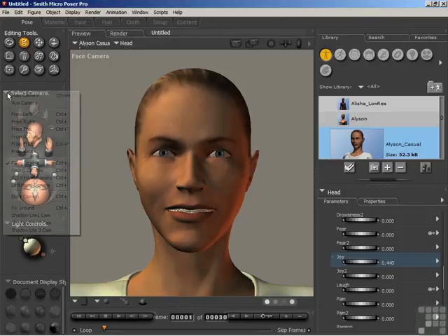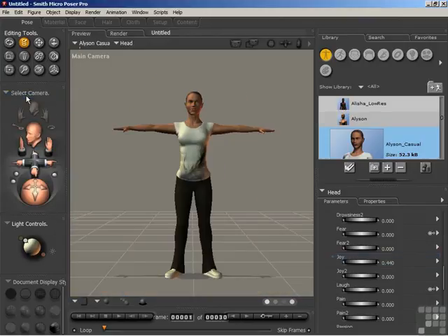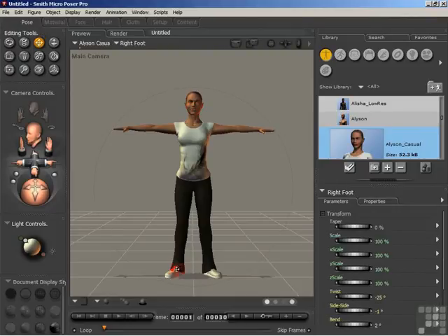Now I'll come into the main view here, and I can also use the Translate Pull button to move the feet. But at the moment, something a bit strange will happen, because I have Inverse Kinematic selected. I can move the feet from side to side, but if I try and bend or twist any of the limb parts of the body, any of the legs, the thighs, or the shins, you'll see that something strange will occur. The limb doesn't appear to be bending.